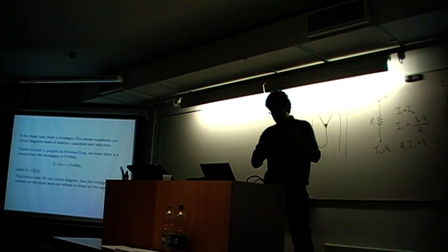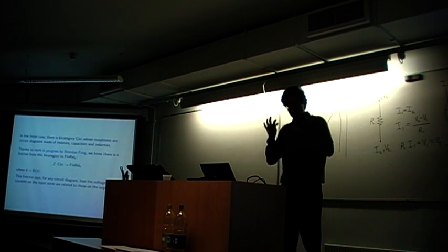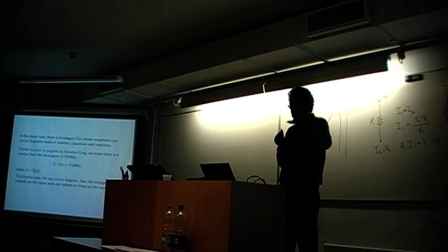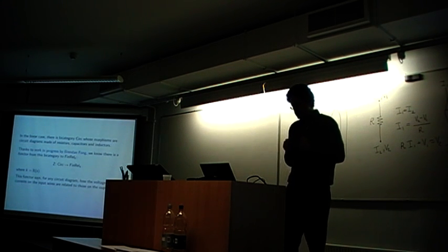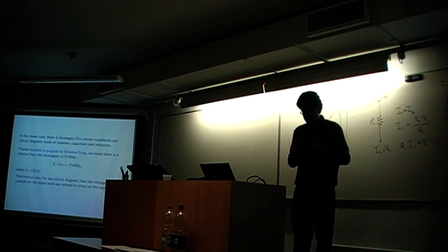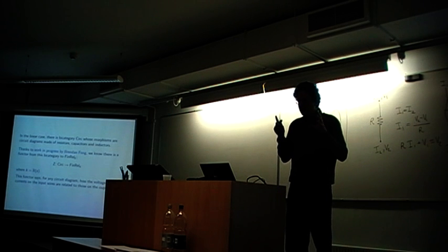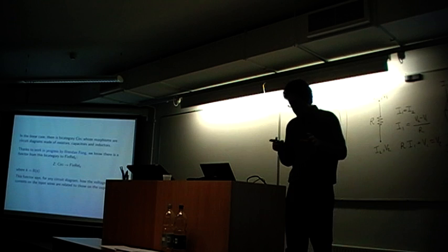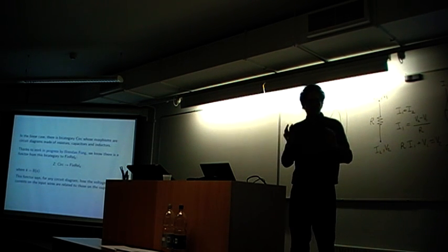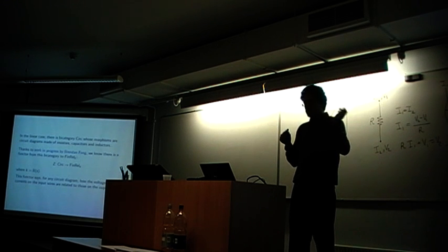And there's a big branch of electrical circuit theory where you say we're not going to consider that because we're going to design machines to be operated under conditions where that doesn't matter. But as you start boosting up frequency so that time considerations matter, then you're revealing that these electrical circuits and this mathematical modeling here is really just an approximation to Maxwell's equations, where you have electromagnetic waves moving around limited by the speed of light.